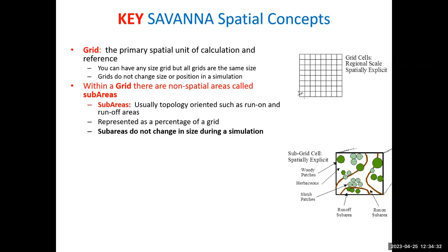They are set, but it allows you to have, let's say, a different soil system on your crest sub-area versus your stream beds, which might have a lot more clay. And you can also put different vegetation groupings in those sub-areas. So it gives you the ability within a grid to simulate different configurations of soil and vegetation.